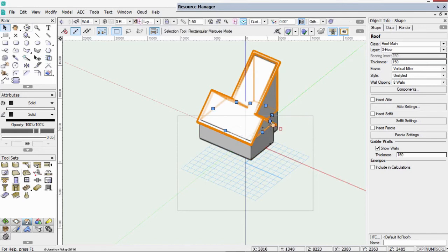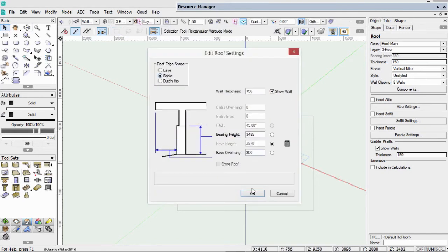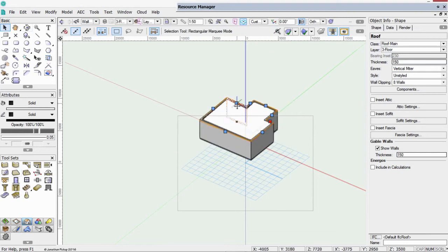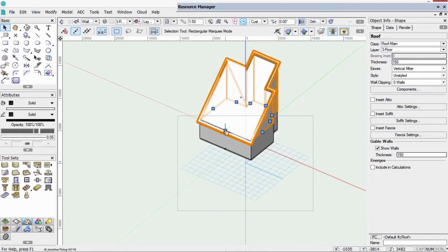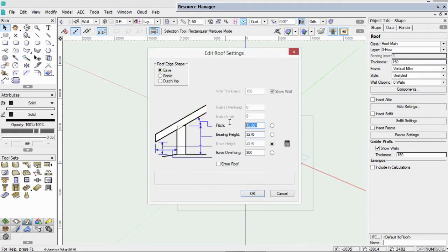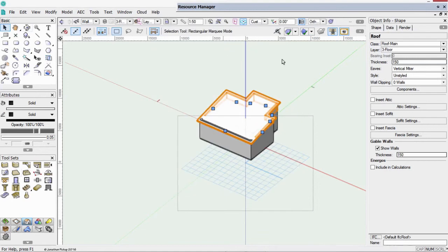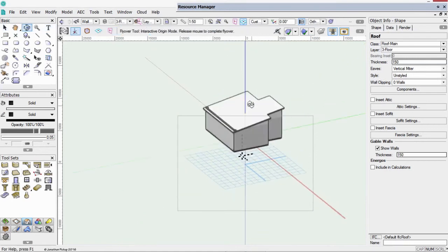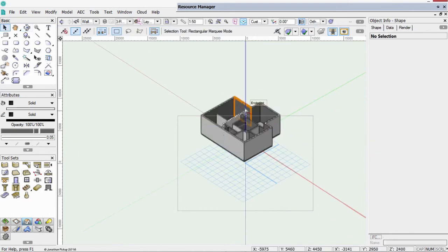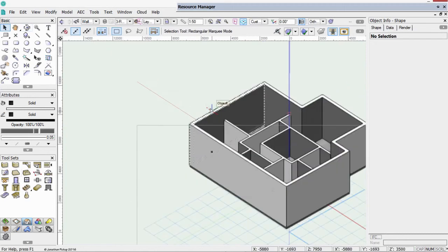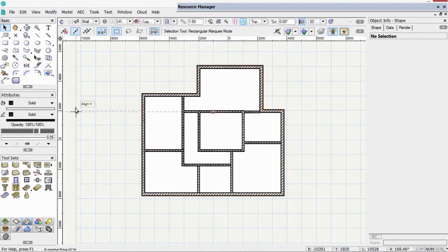What I wanted to show you is that you can keep creating gables until you end up with a mono pitch roof. There we go, I've got an error message there. I'm going to keep going, gable, and now choose that one, change the angle to a low angle, say 10 degrees. So now I've just got a flat mono pitch roof. Let's delete that. I can also draw a polygon and get Vectorworks to build a roof from the polygon. So let's use our paint bucket. It may not be the best way to do it, so I'm just going to use that method.